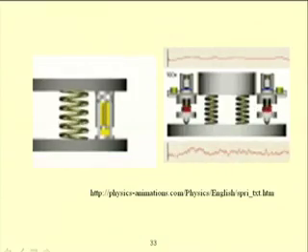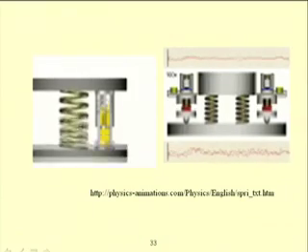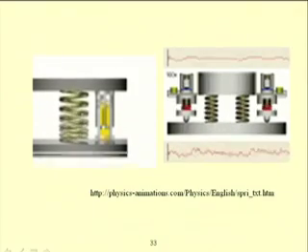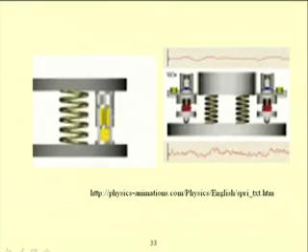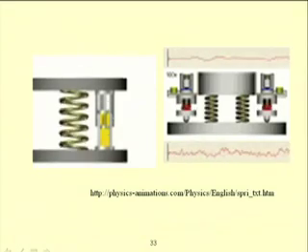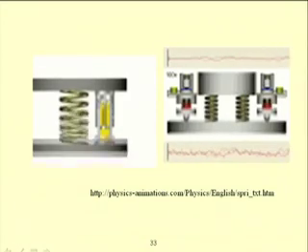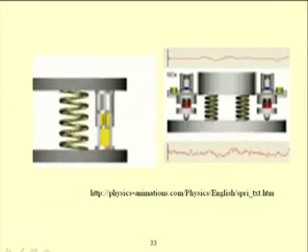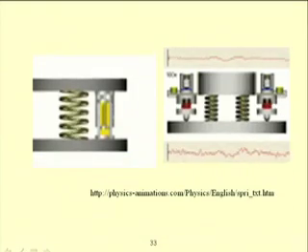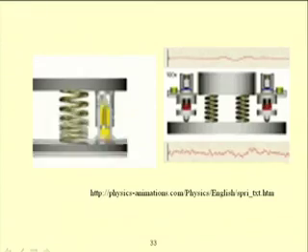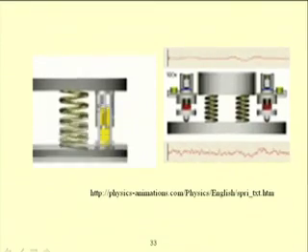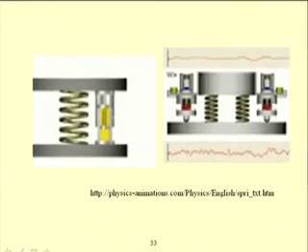Then the spring force will be equal to the stiffness of the spring and the displacement, and the damping force, as one can consider this as a viscous damping, where the damping force is proportional to velocity, so one can write the damping force equal to C x dot. So, the total equation of motion for the system will be m x double dot plus k x plus C x dot equal to 0, if it is free vibration.